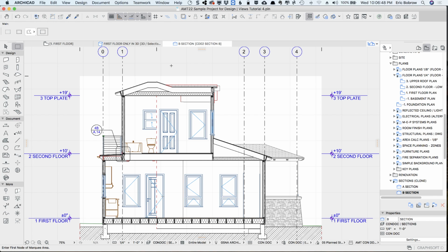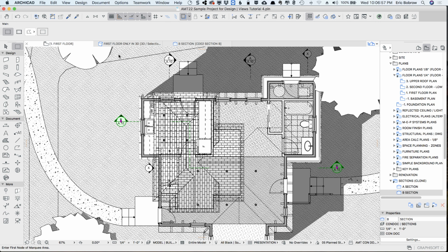So it might be a rather odd jog in terms of this particular building, but it demonstrates something very interesting. I can go and create a jogged marquee to present what this looks like. So if I have the Marquee Tool and I have it in a multi-story mode, and I go to the polygon version, then I can go click on these points here and try to find the snap points.